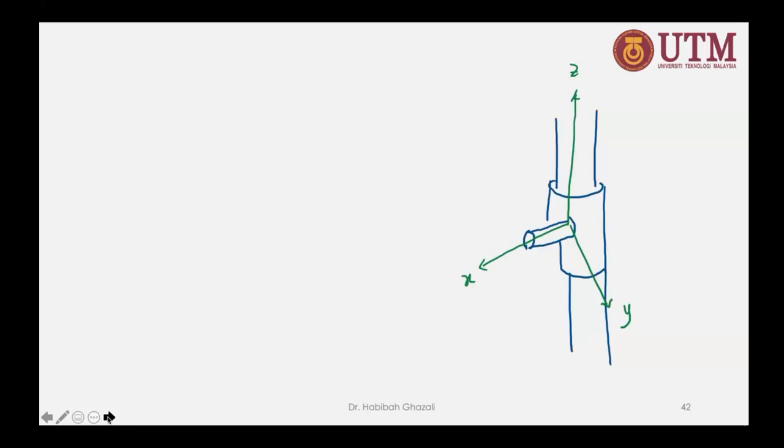This is my beautiful drawing again. It's a pipe, okay? So this is a pipe. And I said that this is my X, Y, and Z direction, for you to visualize it yourself. But this pipe comes with a sleeve. So this is the sleeve that can move in Z direction. So if you want to imagine it, you grab that pipe. Can you move it in the X direction? No, you cannot. So there will be a reaction force in that direction. So I will say it's X.